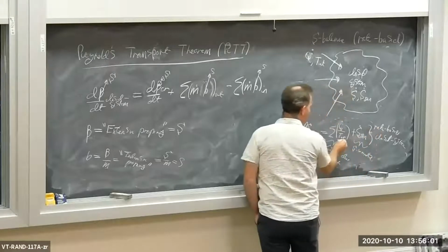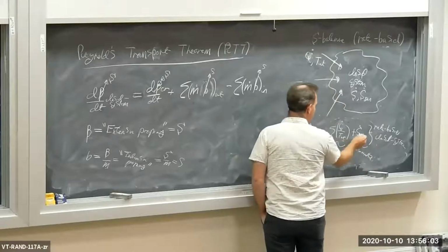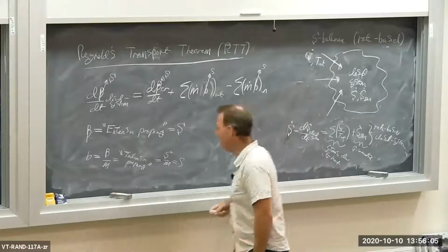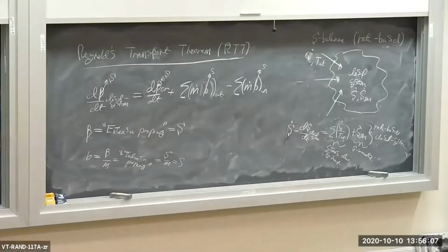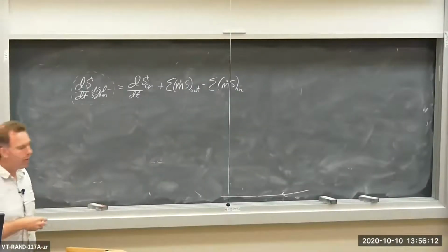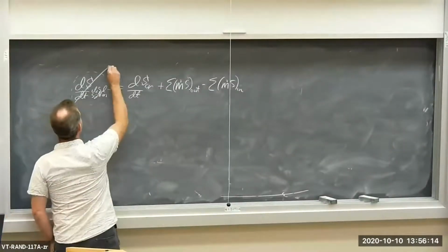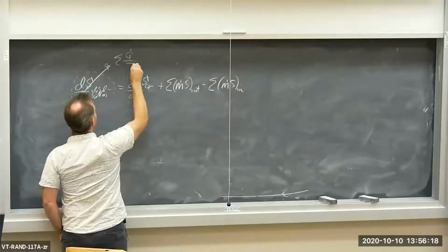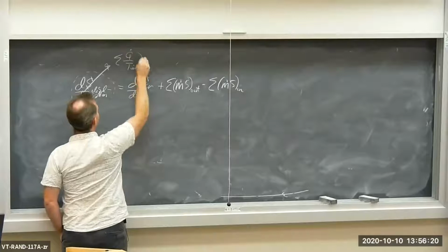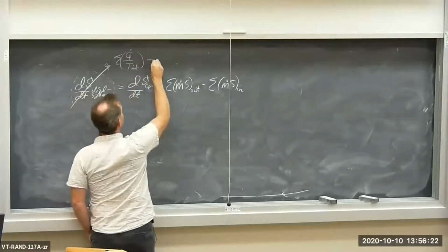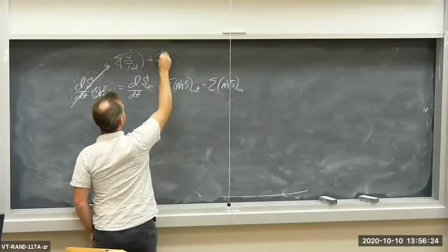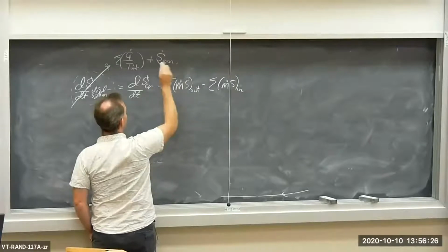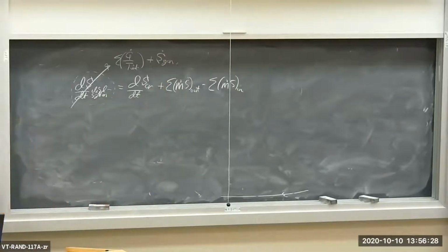We have the entropy transfer due to heat, and we have S dot gen. So I can replace the left-hand side of this equation. So this is equal to the sum of Q dot over T interaction plus S dot gen. And that's from the closed system entropy balance.